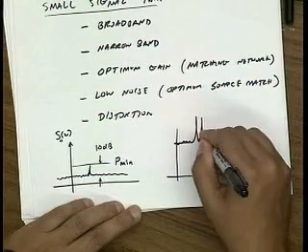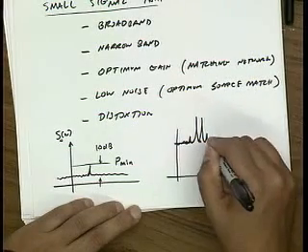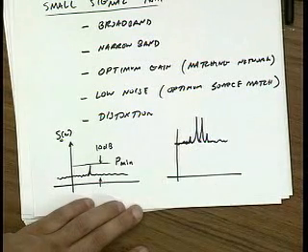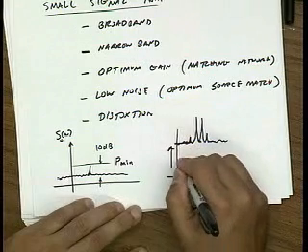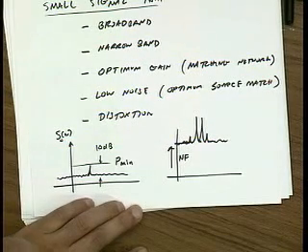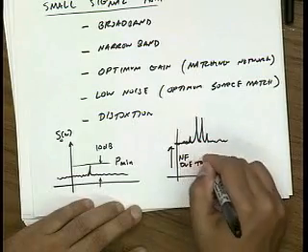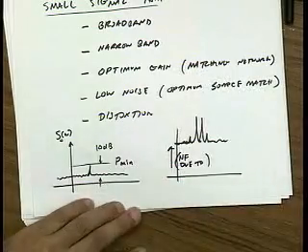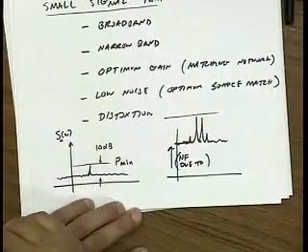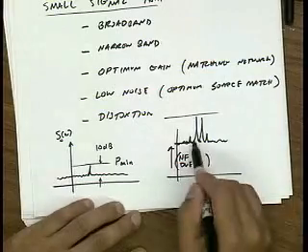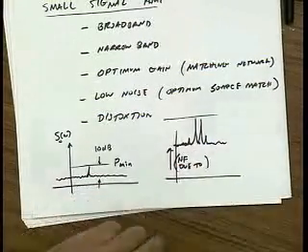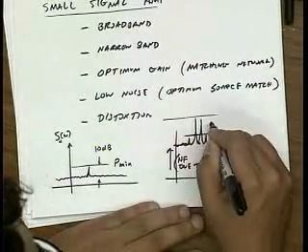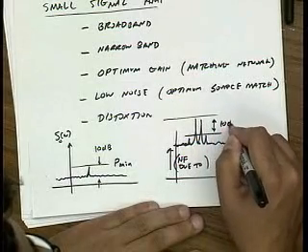let's say I put in two large signals, the noise floor is higher, right? That's because the amplifier has some noise figure. So this is due to the noise figure of the amplifier. It's the degradation of the noise figure that tells you the noise floor growth. Actually, the way I've drawn it, it looks like the SNR is better in this case, but it's not. Anyhow, the important point is that these distortion products begin to compete with your signal.